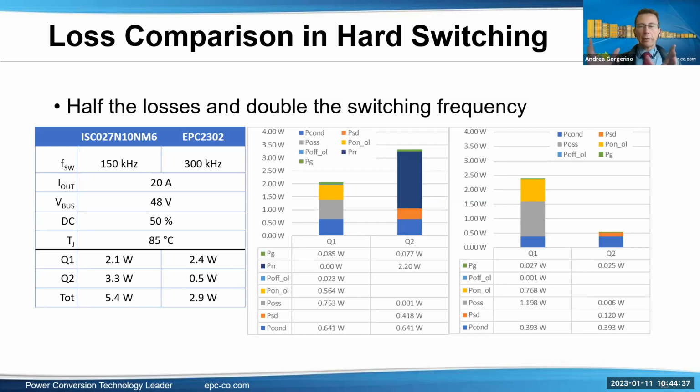And when you use that criteria to define the dead time, which I think is a very reasonable criteria, 12 nanoseconds is a very common number that we use in our reference designs, for example, even less sometimes. Then you get these numbers here, and you can see the PSD, that's the contributor here, is actually lower for GaN FET. That's because the conduction time is so much smaller. So yes and no, basically. But in real application, what matters is the average power loss, not the instantaneous power loss. So the instantaneous power loss is higher, but the average power loss can be lower if designed appropriately.